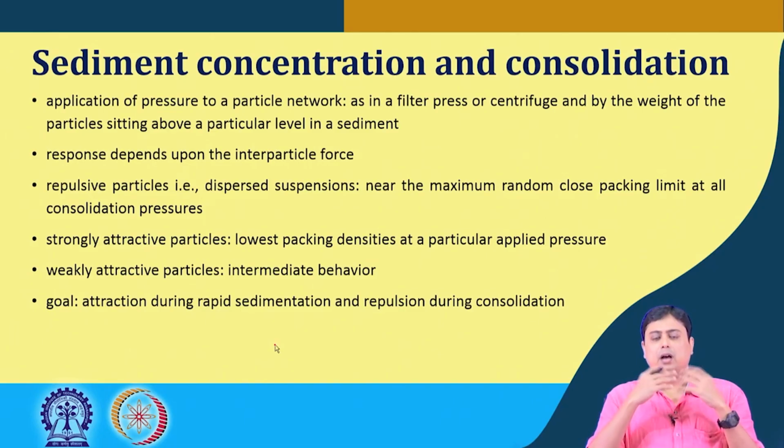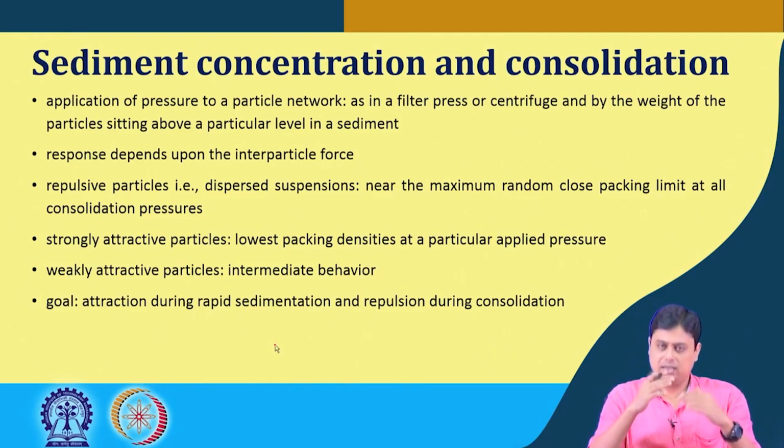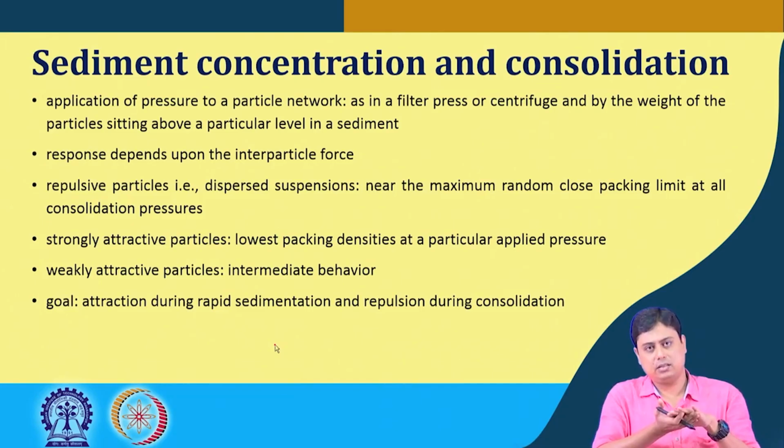Once again, our goal should be to have rapid settling in case of solid liquid separation, rapid settling of the solid particles, and for that we need attraction so that it creates aggregates. But once it settles, during consolidation of this sediment, we want the particles to be repulsive in nature.